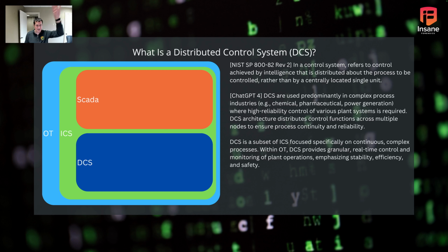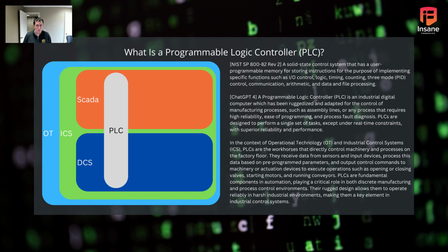Comparing it to SCADA, you're doing it in a small, single geographic area, to where SCADA is dealing with just massive distributed deployments. We'll dive into each of them now, right? So I mentioned earlier the programmable logic controller, NIST definition, right? Single system, generally with user program memory. You have ladder logic on there that gives the logic to the device to act on, to provide certain outputs based on the inputs it's getting, or to interface with the world, right?